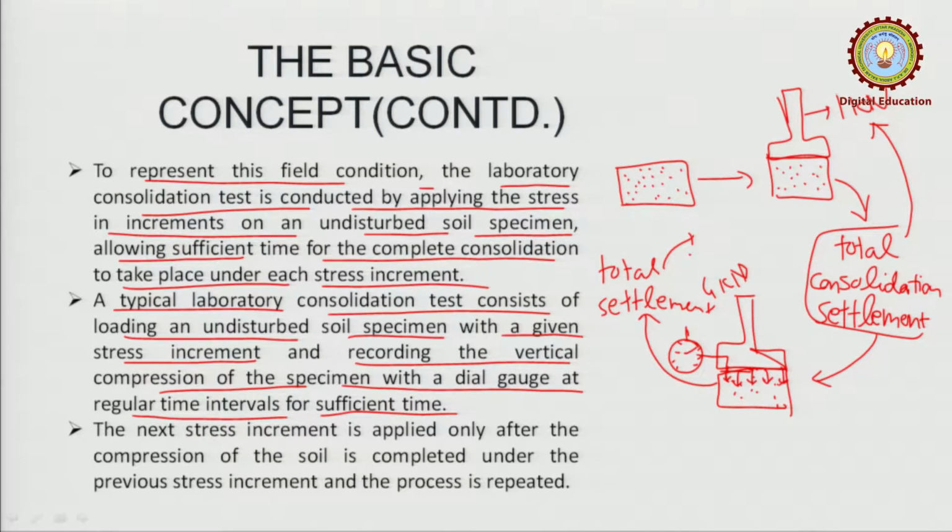of time. Once the load is applied, we will leave it for a sufficient amount of time, maybe 2 days, 1 day, or whatever may be the case, depending upon the soil as well, okay. So, we will leave it for a large amount of time, and at regular intervals we will take the dial gauge reading, to see how much settlement has taken place. Then continue with an increment of the stress afterwards only when this dial gauge shows no further settlement, okay.